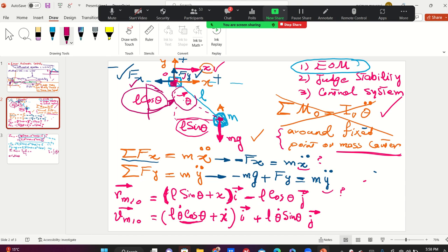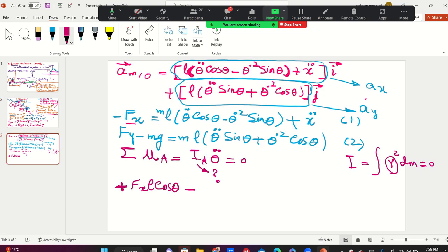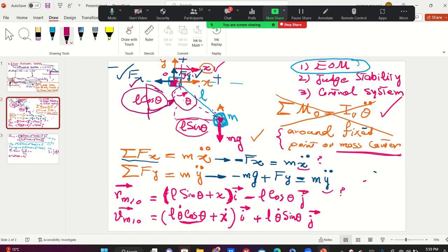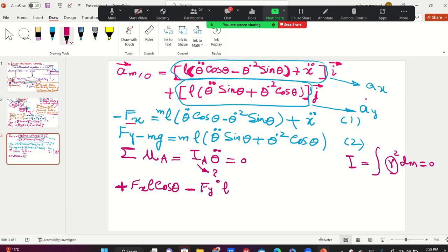Okay. Good. Now Fy. Again, I'm fixing this on the space by my finger. If you apply Fy, this link is going to be like this. That's right, so you're decreasing the angle. See, the angle is being decreased, so you're resisting the motion. Resisting means negative. Fy in the normal distance. The normal distance is this, L sine theta. L sine theta is 0.